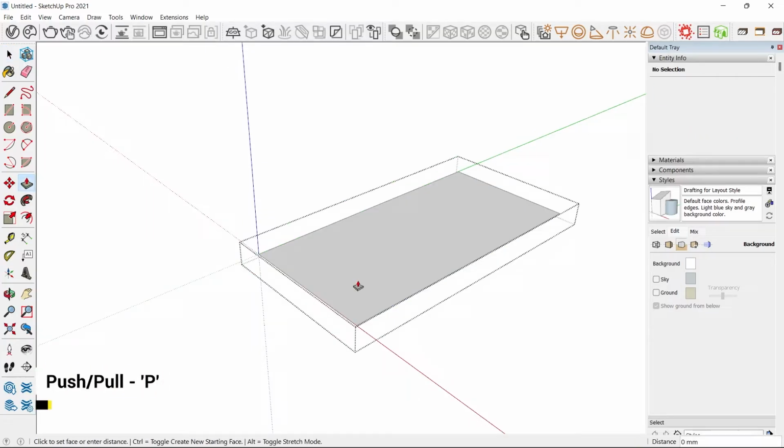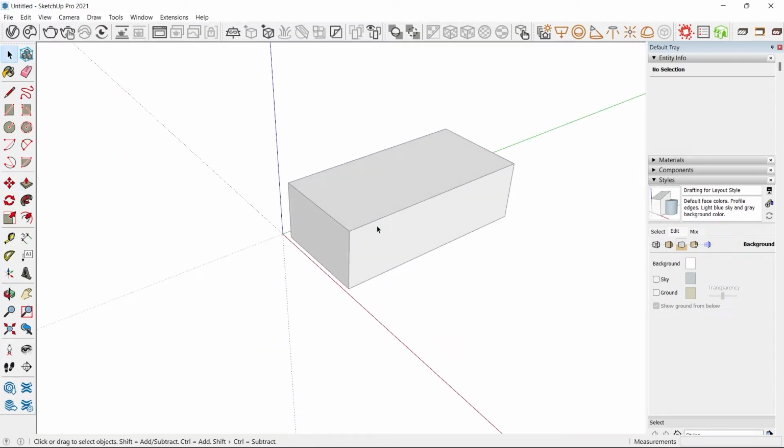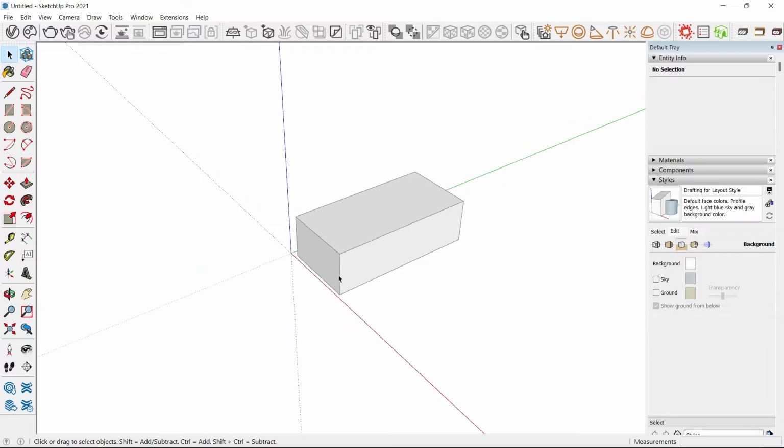And then I can enter the group, push this out. Now if I want to hide this, I can select this group and press F2 to hide, or you can press Ctrl 1 as well. And then you can press F3 to unhide last and F4 to unhide all.